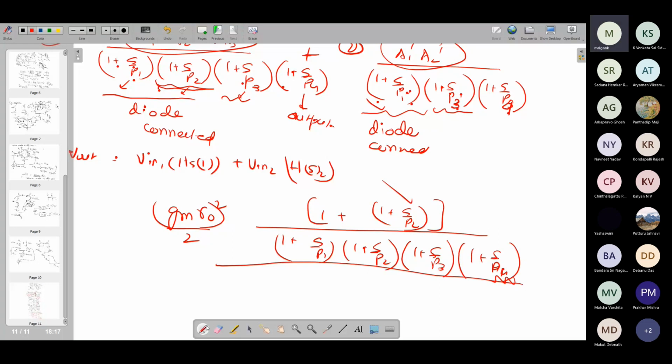So this is just to show you that in a circuit like this, how do we do the frequency response? For a single stage amplifier or multi-stage amplifier, I have already discussed. But here we have a differential amplifier where the two paths are not symmetric. We need to follow the signal path and figure out the frequency response for both the signal paths, and then add them together and figure out the overall frequency response.